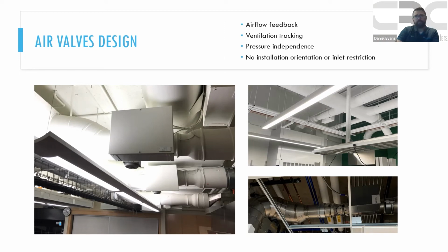But the one I talk about a lot is the large one on the left side of the screen. We see a bunch of air valves coming in, and in this particular case, what worked out well is they had a very difficult ability to run ductwork and get their flow rates. If we look at this back air valve that's now been circled, we come out of a fume hood at a 12-inch collar. We instantly go to our short radius 90 that turns from round to rectangle, and then we take a rectangle right into a round transition right into the front of the air valve.